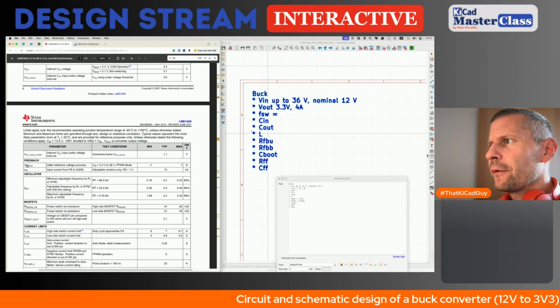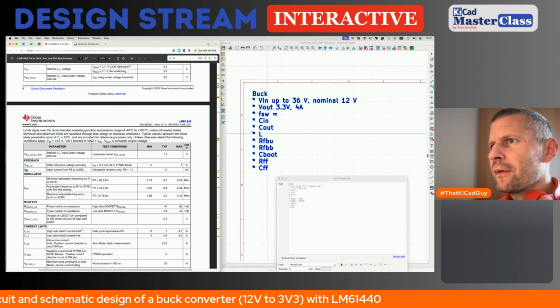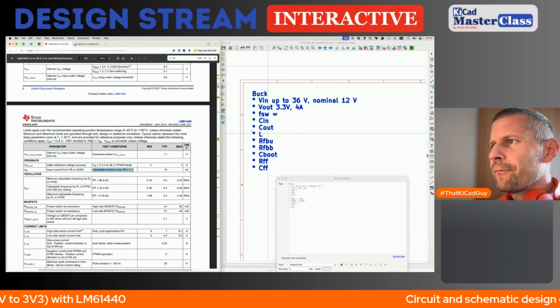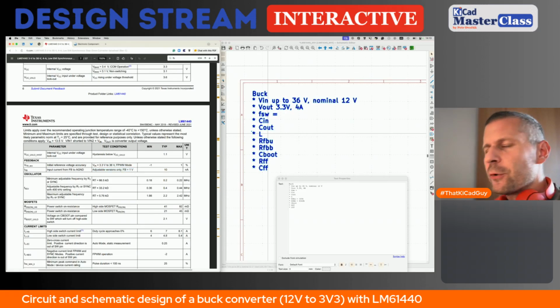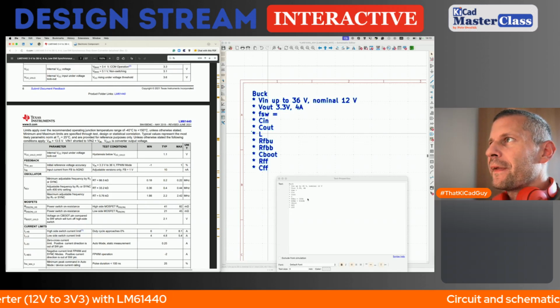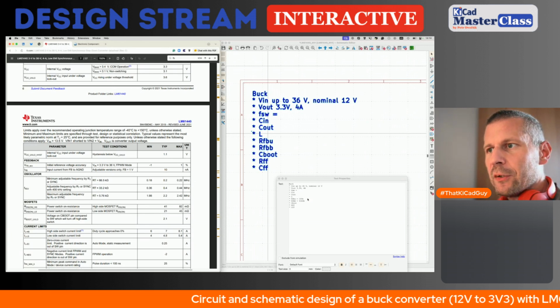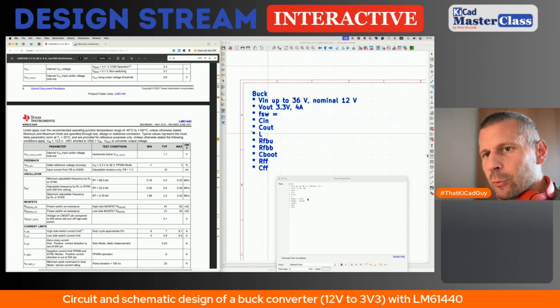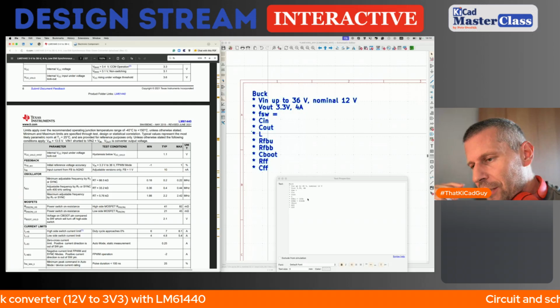Here, feedback. No, this is the initial reference voltage accuracy. Adjustable versions only. Feedback is 1 volt. So this is the feedback voltage, 1 volt. If you want to calculate your own voltage divider, you basically have two unknowns, the top feedback resistor and the bottom one. You know the supply voltage of the voltage divider, and you know the output voltage of the divider.